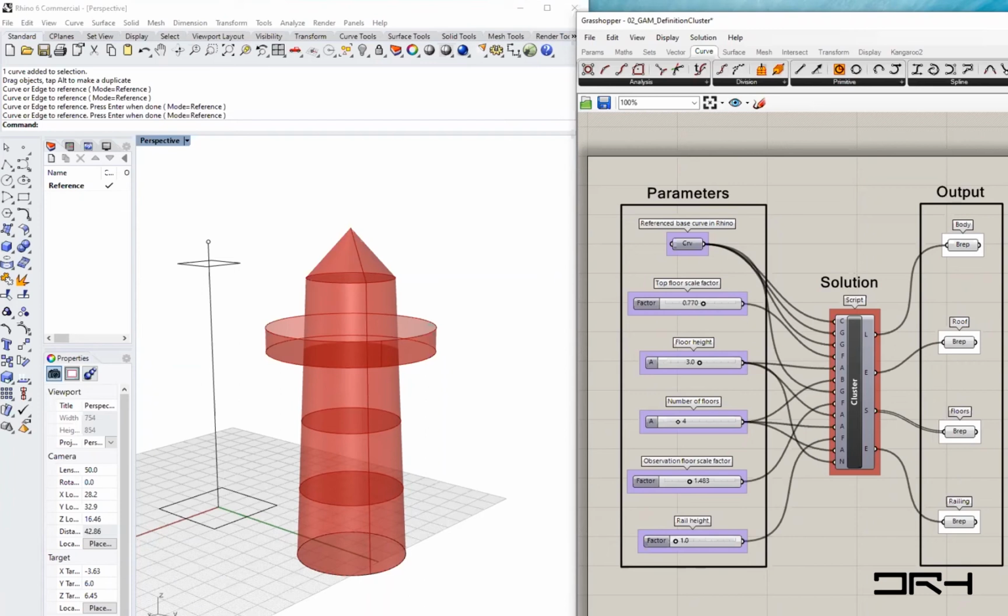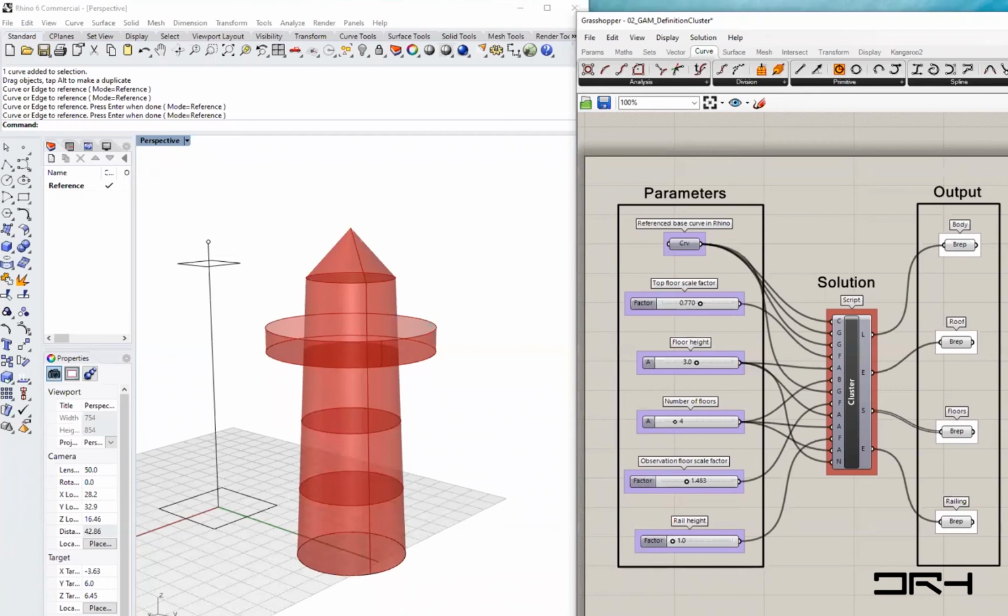Yeah, I think usually a combination is the best. For example, you saw the staircase that we had. You can take a component or part of your model and do it in Grasshopper. Or maybe you have a sophisticated wall art that uses certain curves that need to be controlled in a certain way. You can have a feature within your model that uses Grasshopper that is hard to model and modify within Rhino. And this is typically the best way to go about it.